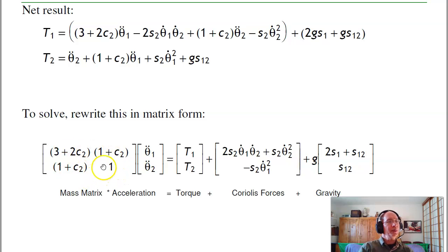If the mass matrix ever goes to 0, like if you have an ice skater and you point your arm straight up, I become a line, in theory, which would have 0 rotational inertia. If the mass or inertia ever goes to 0, the acceleration goes to infinity. Again, energy has to stay constant. And I have these gravity terms. Basically, a robotic arm is highly nonlinear.